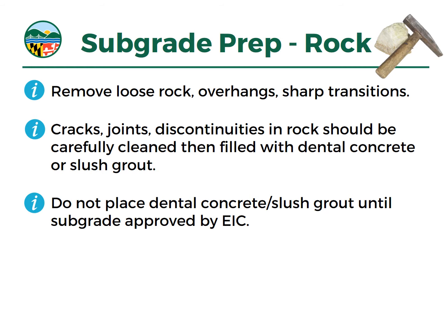Some specifications will be pretty detailed, calling for water jet cleaning of any clay infilled seams or joints. We've seen people literally with shop vacs cleaning out and preparing the subgrade in a rock foundation, so it's really ready for acceptance of the embankment fill material above it.